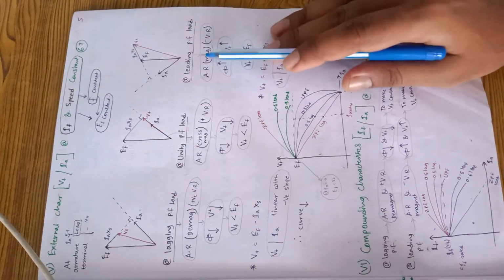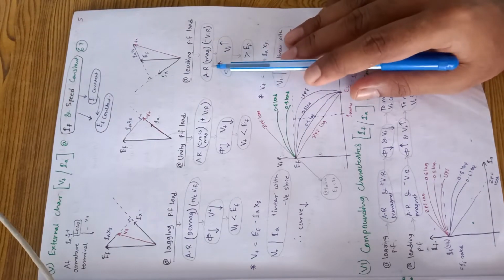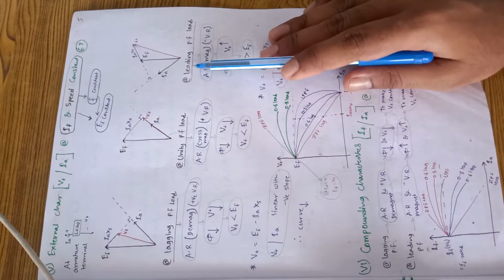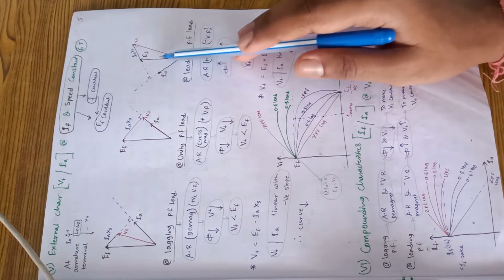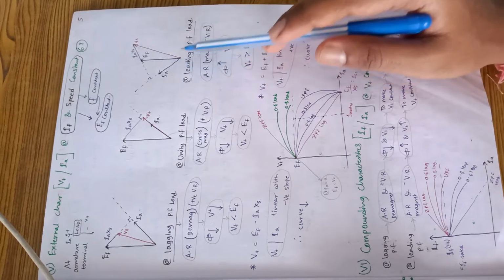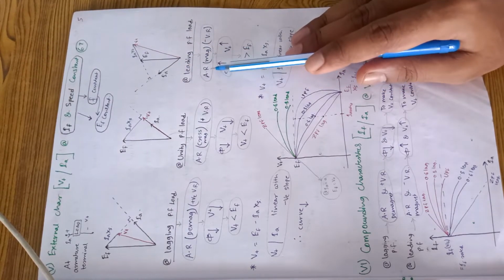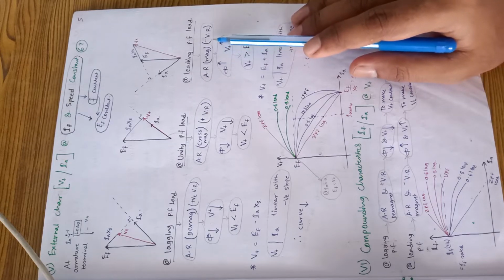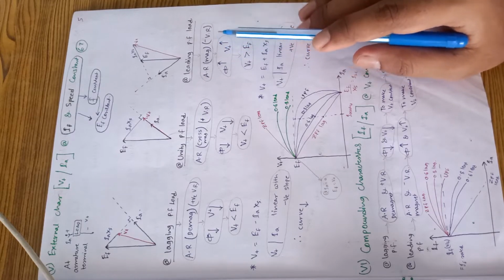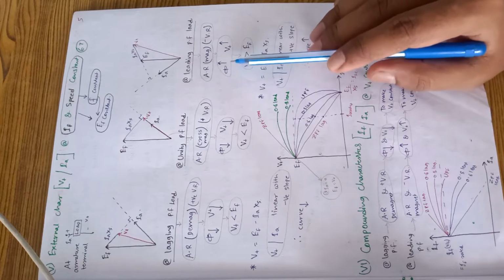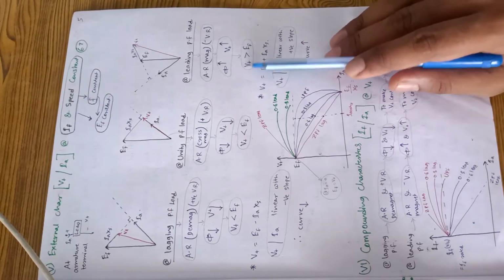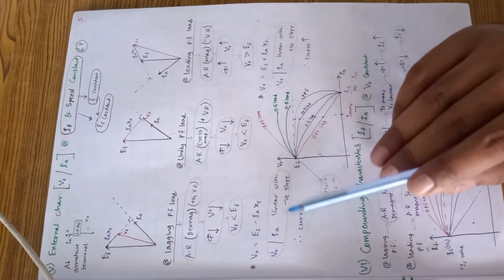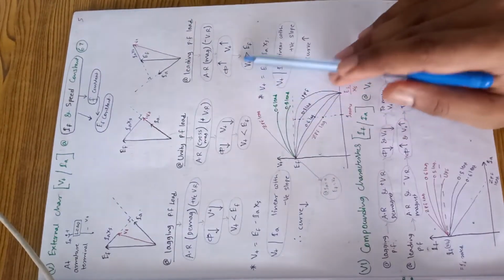Okay, remember that. And when we talk about armature reaction for leading, the current is leading the terminal voltage and Ef. So armature reaction is magnetizing here, and magnetizing armature reaction means negative voltage regulation. Magnetizing means phi will increase, Vt will increase, therefore Vt is greater than Ef. Correspondingly, we understood all these things.